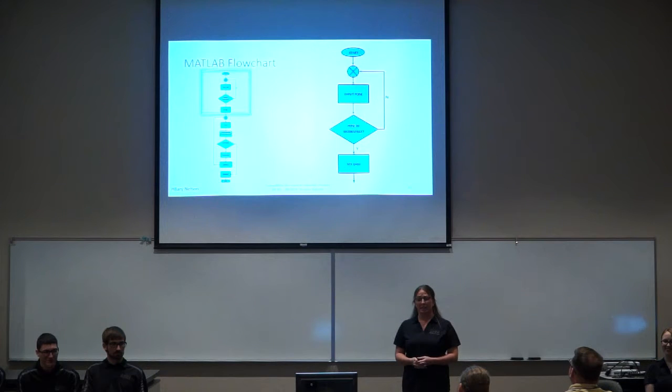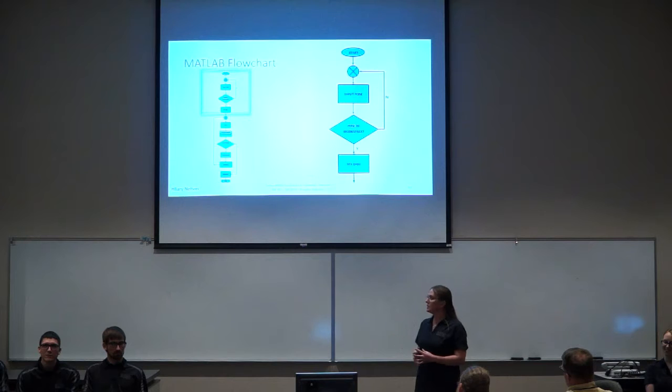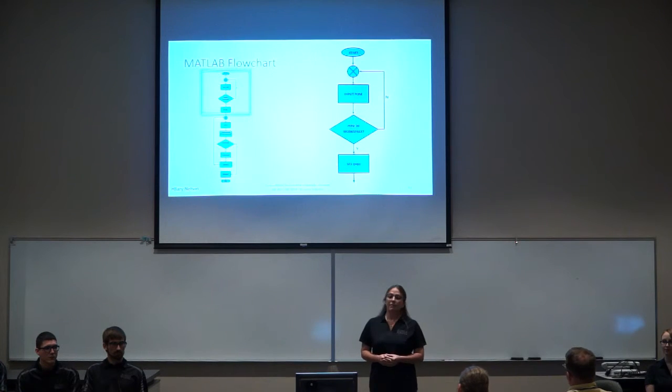After initialization of the program, we enter into the program to check to see if the pose is within the robot's workspace. If it is not, we prompt the program to start over again to find a pose that's within the robot's reach. After we find that the pose is within the workspace, we set up our configuration vector, which is a vector of joint angles.